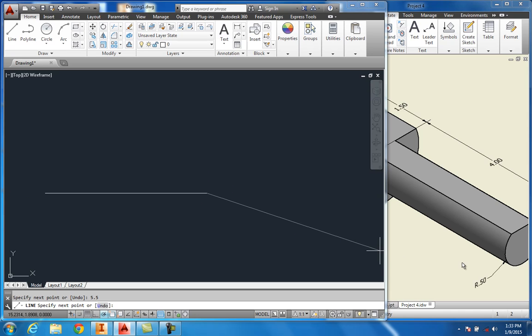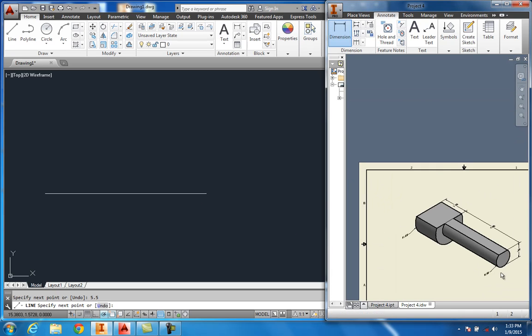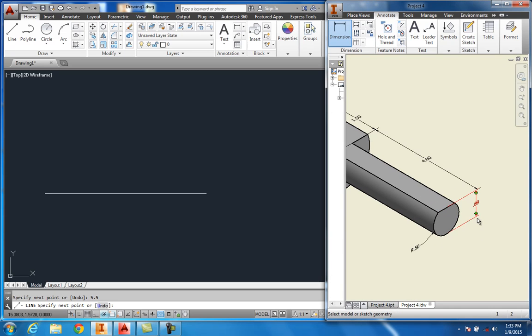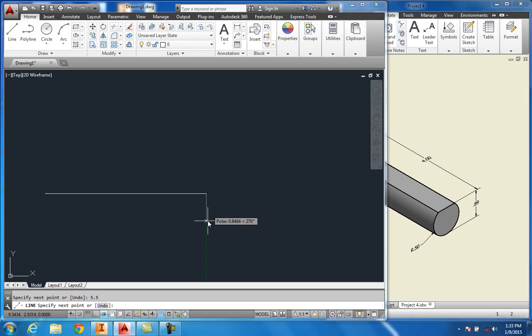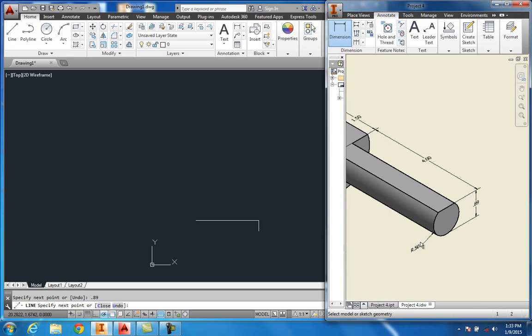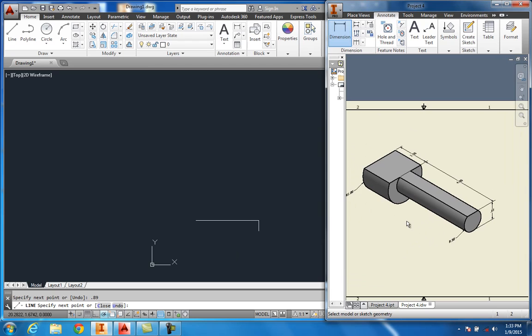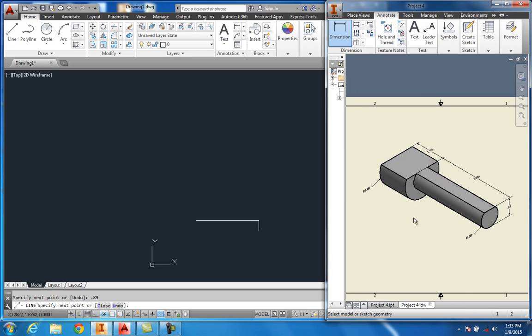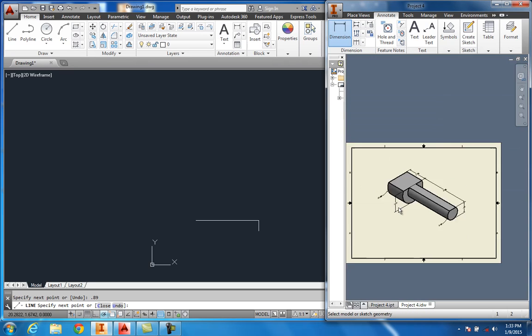Alright, now the diameter over here, well, from the top of it to down here is 0.89. So come over here, direct line method again, 0.89. And let's see what else we've got. And I'll need a dimension over here, going off the main top there to the midpoint there. It's not exactly the way that I want it to dimension though. And it looks like 1.39.